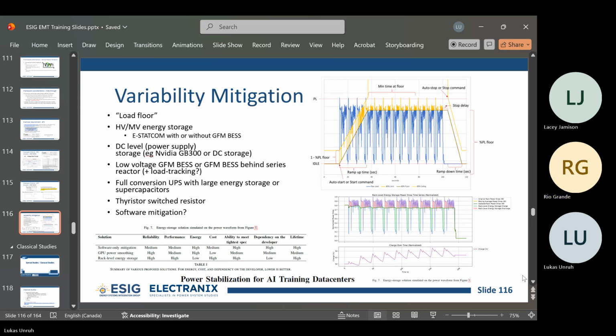How about thinking of how much of the load you adjust in your output, instead of fully on or fully off? Say it's a 1,000 megawatt load at a bus, and the voltage is 0.9 for X seconds, and then you come offline, all 1,000 megawatts. Now the voltage is even higher then.